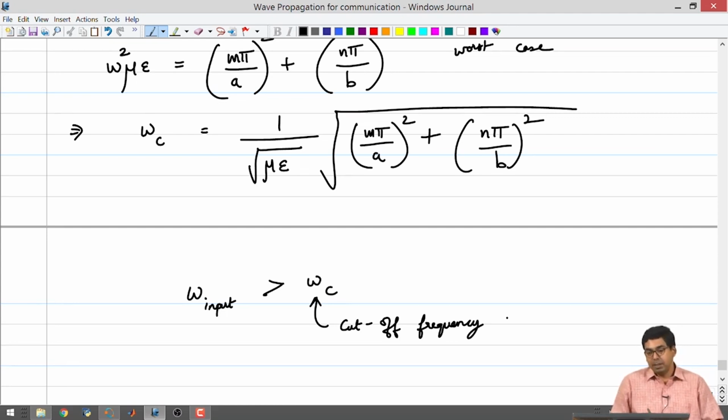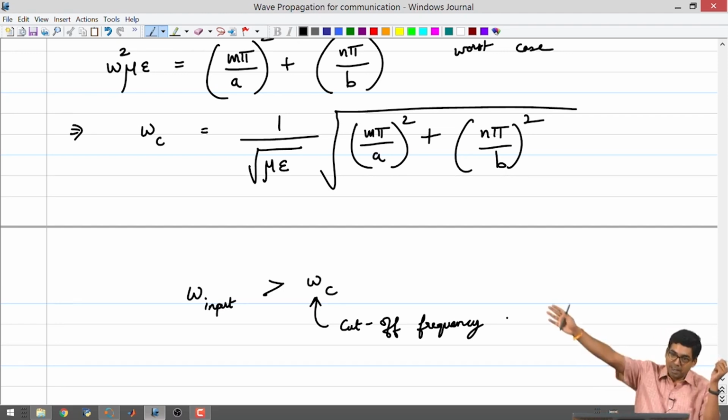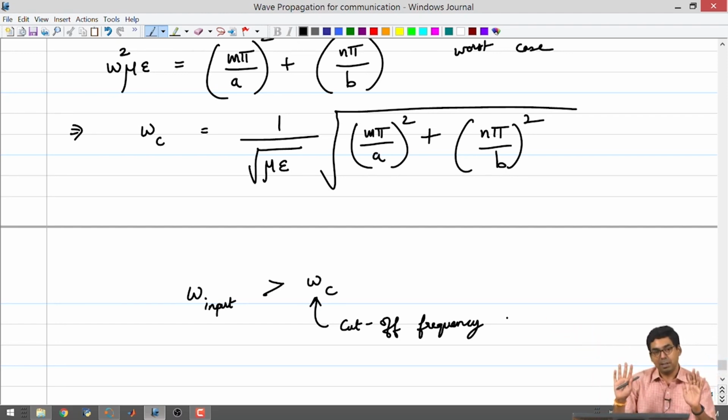These two cases are very similar, parallel plate and rectangular, just that the parallel plate was very easy to analyze because it had only two interfaces, but now you have many interfaces coming into the picture. So, we had used a different approach. We started with the general solution and then we tried to see, based on the standing wave patterns and the travel direction, what kind of approximations you can make and come up with a solution that actually seems to be valid: travelling wave in the z direction, standing wave pattern in the cross section.